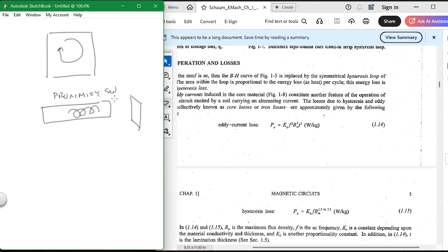Okay? When you have a piece of metal in a furnace and you're inducing voltage to try to get it hot, these eddy currents in the metal are what make it hot. So it's these swirling currents that make it hot. Okay? Now, why do we have laminates in motors?